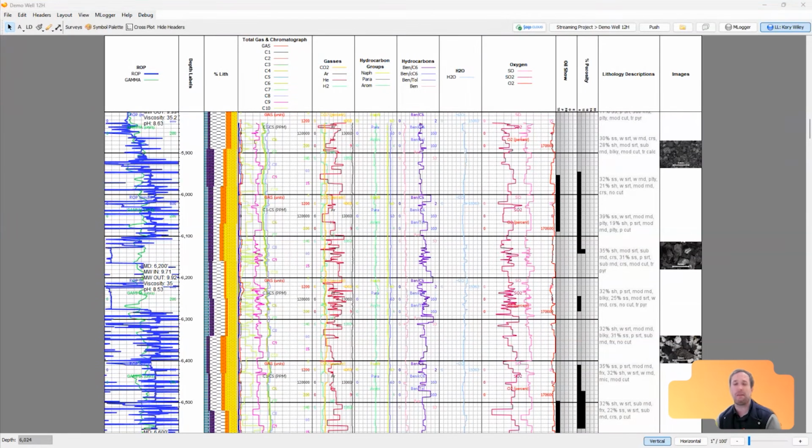And the mudlogger is not just collecting lithology data like we could think of. They're also collecting gas data. They can be collecting XRD, XRF data. They're collecting data about the mud weights from the mud engineer. They're looking at some drilling data like weight on bit, RPMs, all that kind of data. They're compiling it on what we call a mud log, and they are then giving that information to the geologist. So it's not only lithology data, but it includes a lot more information relevant to operations.